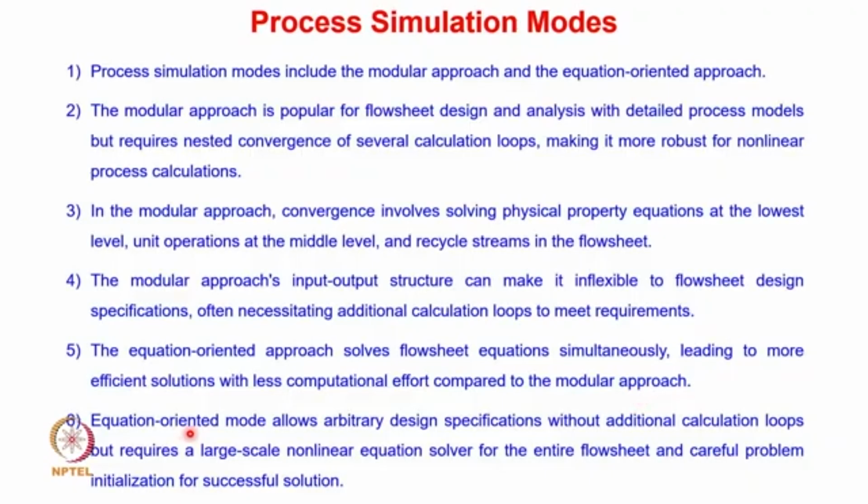That is also important. Sometimes these non-linear equation solvers can diverge also. Okay. So equation oriented mode allows arbitrary design specifications without additional calculation loops, but requires a large scale non-linear equation solver for the entire flow sheet and careful problem initialization for successful solution.